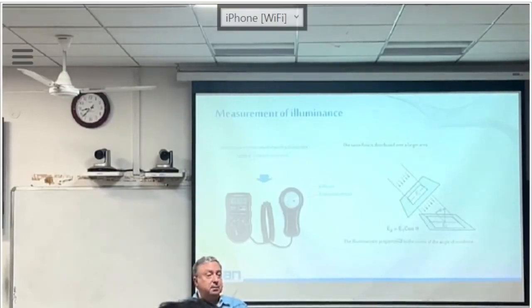What is the difference? The more expensive one can measure other things, not only the illuminance, such as color, other things that you may need, but it is calibrated. That means what you measure is a good value. The very cheap instruments, less than 500 euros, are not calibrated, because a single calibration point is globally 500 euros. And normally in a metrology lab, you have to calibrate all your instruments at least one time per year and have the calibration certificate.